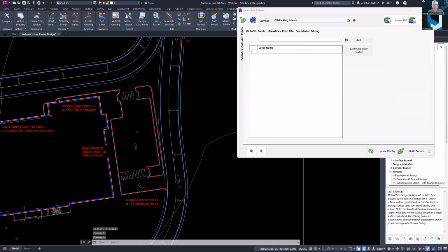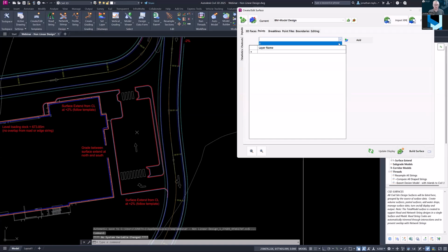this goes on to my point about drainage. In your built model, not many people realize, but you can add 3D faces, points on layers, break lines, 3D polylines into a model builder model. So if you've got a third party or somebody else who has designed and they can give you 3D polylines for your driveway design, wherever it happens to be, you can incorporate them into a model builder model. And I could use that CAD point there with an elevation and use its layer, which you can see is layer 0, bad layer control, and that would be modeled. There'll be a triangulation to that particular CAD point.